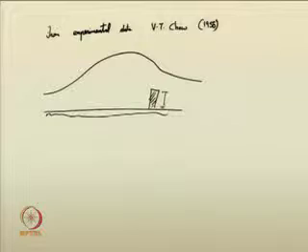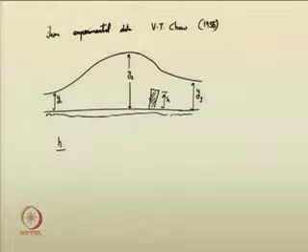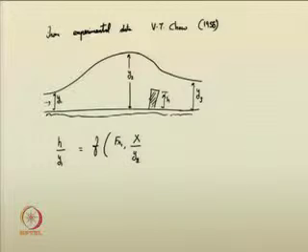There are the following parameters: the height of the sill, the pre-jump depth, the sequent depth of the jump and the tail water depth. These 4 depths are present in such control mechanisms. From various experimental studies, it has been observed that the ratio of the height of the sill to the pre-jump depth is some function of the incoming flow Froude number, that is the Froude number at the pre-jump depth section, the ratio of x by y 2 and the ratio of y 3 by y 1.